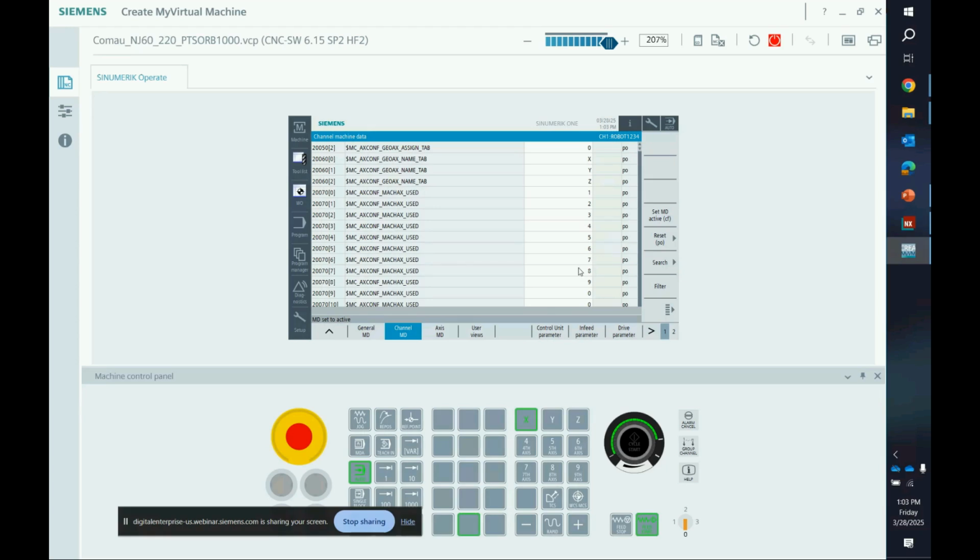If I added a second channel to this Numeric 1, I could drive 2 robots and the positioner with one motion controller, with one NCU. Maybe you hit some processing issues depending on how complex your CNC motion is, but that's one way to do it. One Numeric 1, 2 channels driving multiple robots.